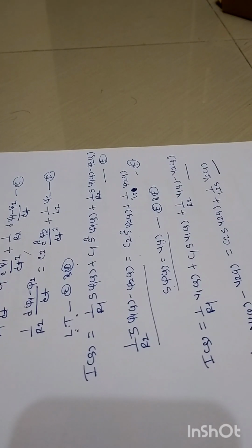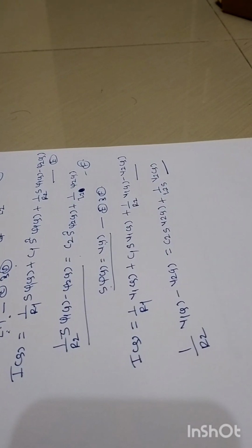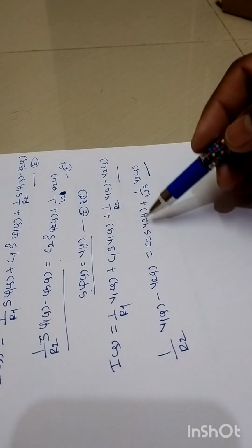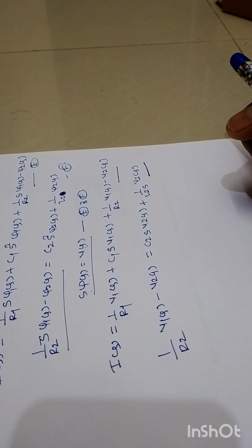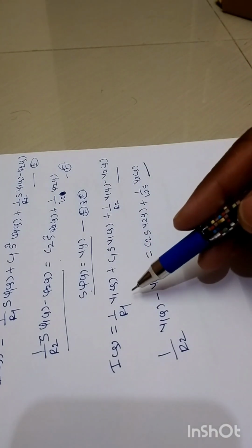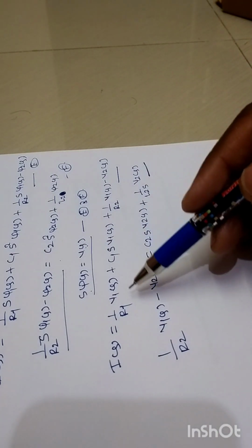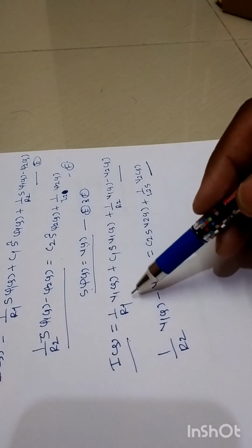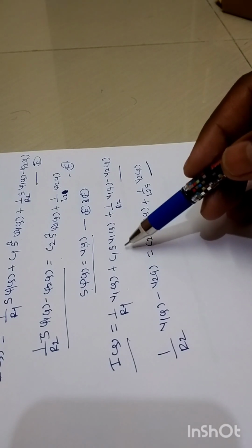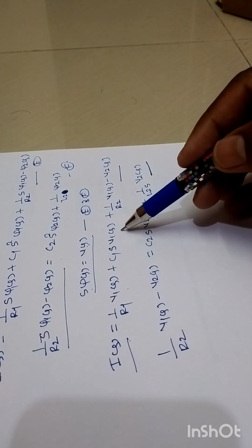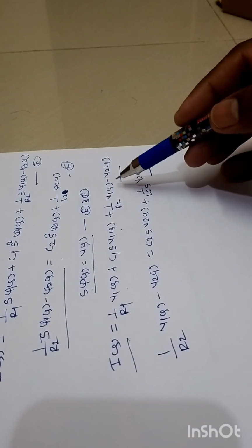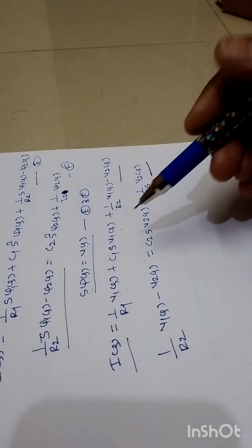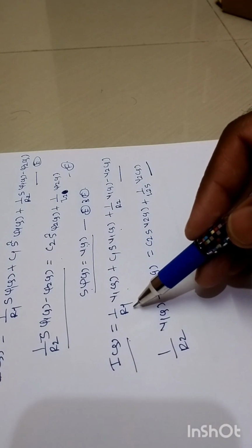So now it is very easy for us to draw the force analogous equivalent circuit from these two equations. Carefully when we see these two equations, as far as the first equation is concerned, I of S equals 1 over R1 into V1 of S plus C1 S times V1 of S plus 1 over R2 into V1 of S minus V2 of S. Carefully try to see the coefficients of these terms.